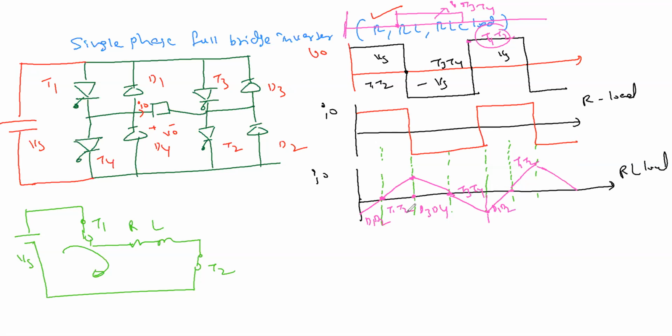So it is an RL load. When it is an RL load, at that time the thyristors T1 T2 or T3 T4 or the switches do not start from here at 0. Here now you can see it conducts, T1 T2 and D3 D4. So in one cycle it is half, it means 50-50 you can see here now. Previously what we did, from here the entire positive cycle was T1 T2, now T1 T2 and D1 D2 are sharing.